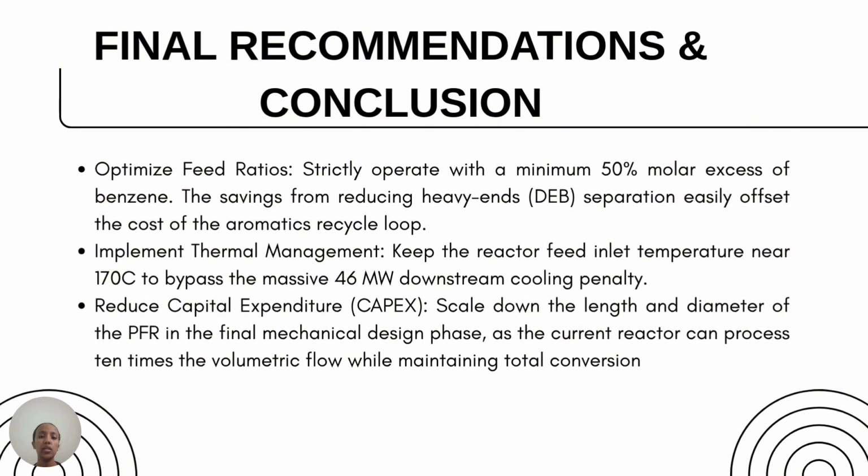And yes, this means we'll need a recycle system, but we think it's worth it because we can reduce the formation of the unwanted DEB. And second, for temperature, we should stay at around 170 degrees Celsius, because increasing the temperature doesn't really improve the reaction so much, and it just creates more cooling work later on.